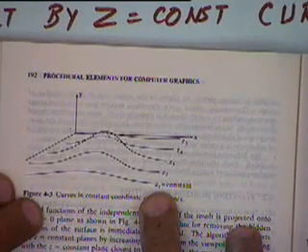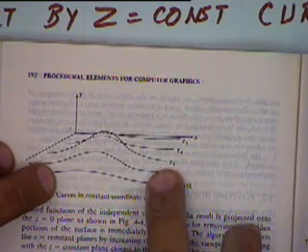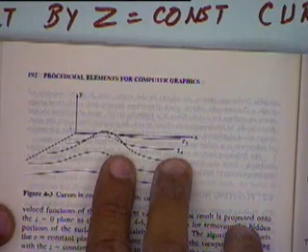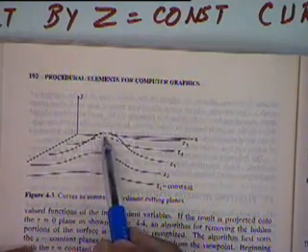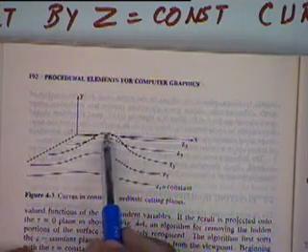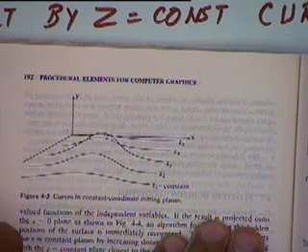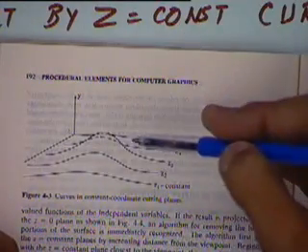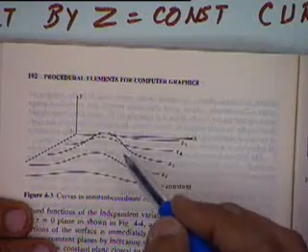Look at this figure. Here z1 equal to constant is the first curve, then you have z2 equal to constant, z3 equal to constant, and then at z4 equal to constant, a part of the curve is going underneath. That has been shown as a dotted line. That is this part of the curve. And again z5 equal to constant is again going dotted. So this way, by taking successive planes, we are able to get a three-dimensional kind of effect by showing the back portion of this hillock as dotted lines.